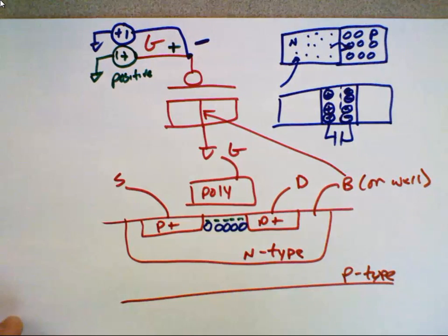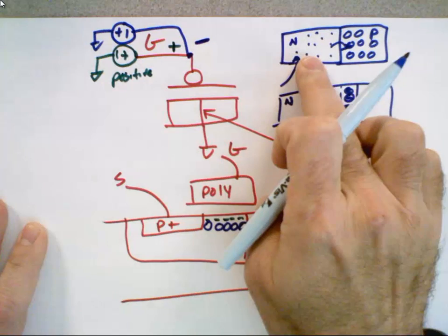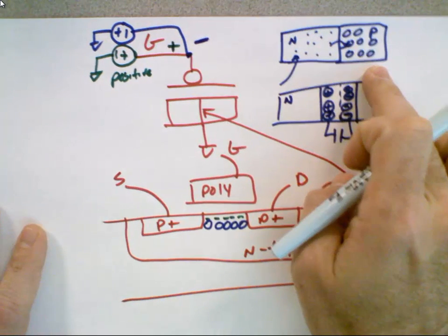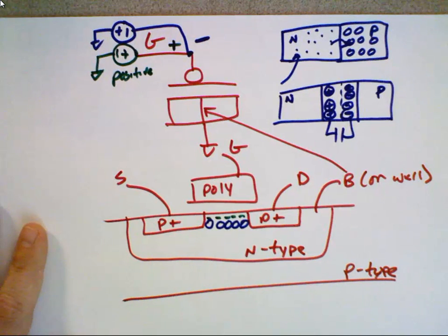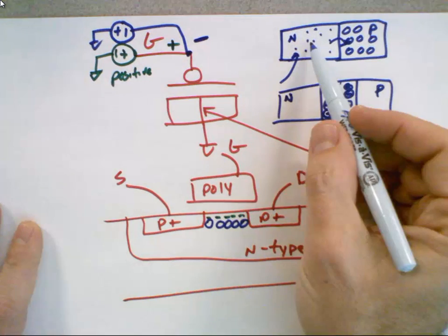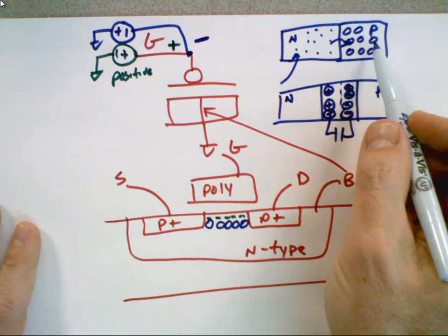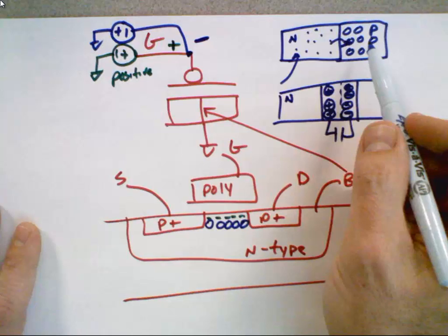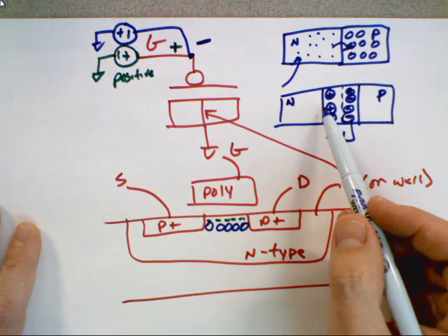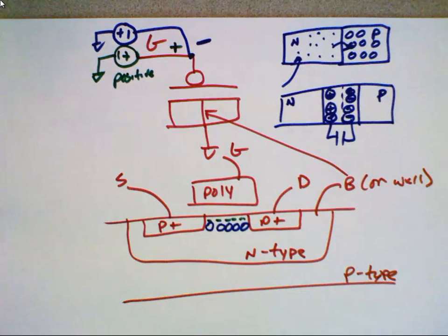But one more question before we move on. Why don't all of the electrons from this side move over and fall into all of the holes over here? I mean, doesn't that make sense? When I was learning this, that's what I wondered. Why don't all those free electrons fall over and go into the open holes over here? Well, when that atom loses its charge, it says, hey, come back, and it equalizes. So you can't lose too much before there's too many atoms trying to pull the electrons or repel the electrons back. Okay? There's this fixed amount of charge there.